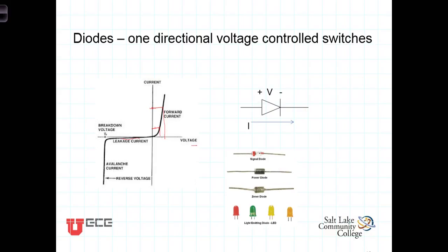current through them. Now this model here, or this voltage-current relationship, is actually an exponential relationship where the current is equal to some initial current I0 e to the, we'll just call it V. We'll just leave it at that for now, so that what we're representing is that the voltage across here is the exponent in this function, and very small changes in V represent very large changes in current. And this is the best model that's out there.